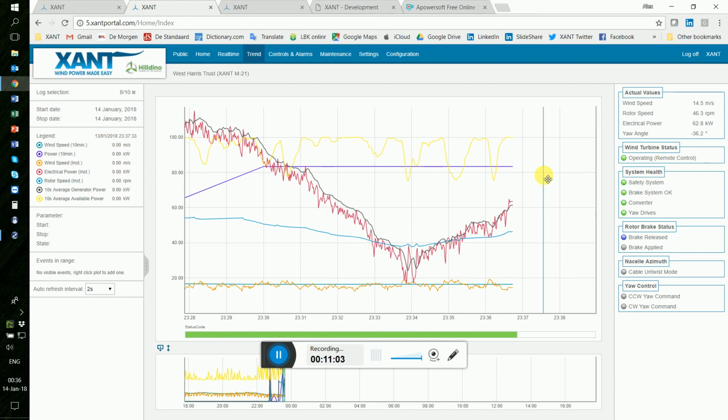Again, this is a feature that's perfectly capable of being triggered remotely by an energy management system, effectively smoothing and reducing the power output of the wind turbines. You see the ramp up of the power, 80 kilowatts, and almost back to rated power.